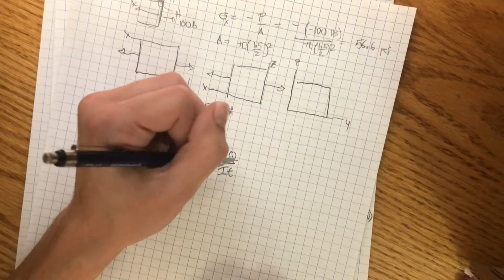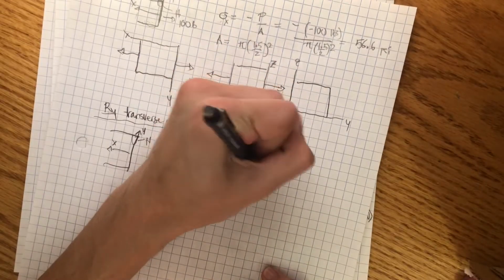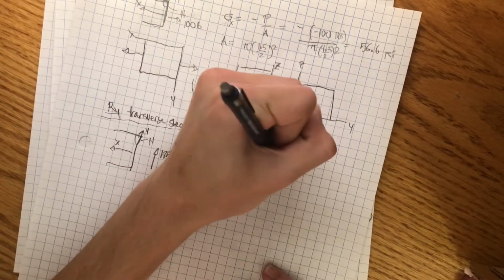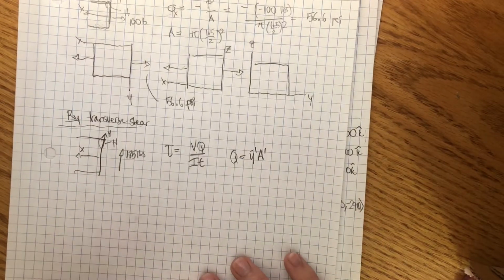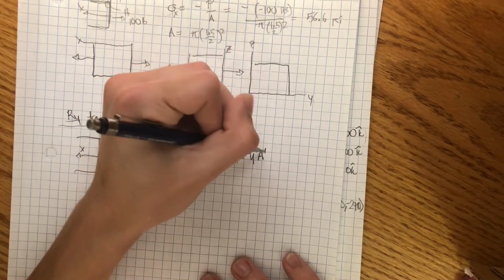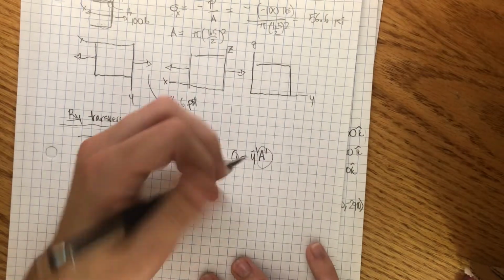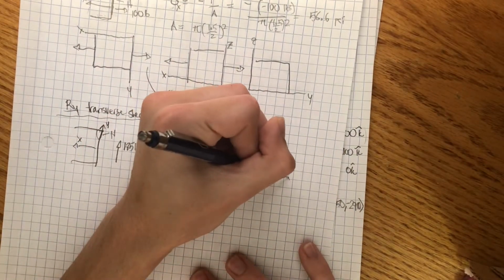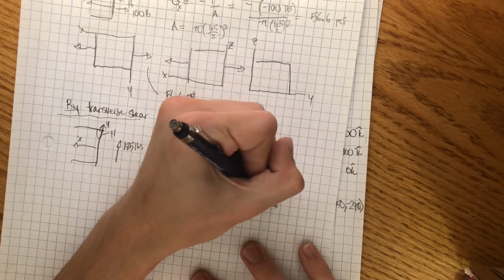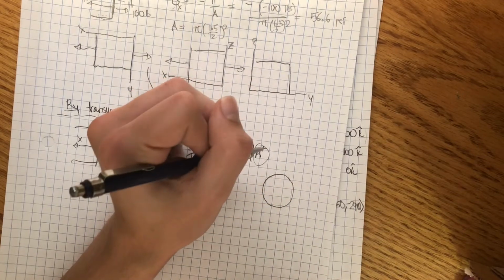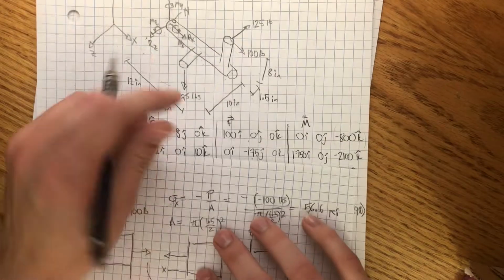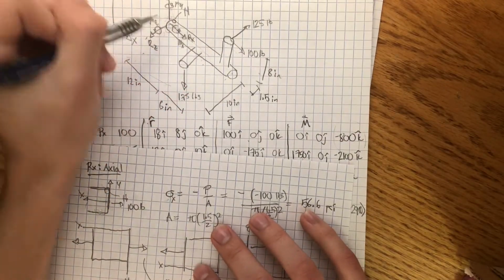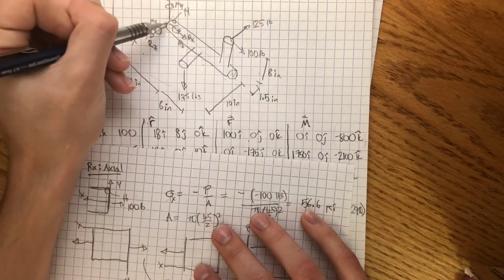And now the first moment of area here, Q, is equal to y bar prime times A prime, right, like that. This value here is the area, the outer area from our point of interest when you were looking at the cross section. So as if you cut it and you were basically looking at that face, but right here.